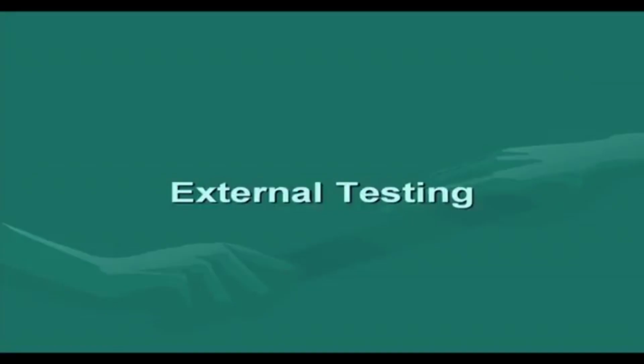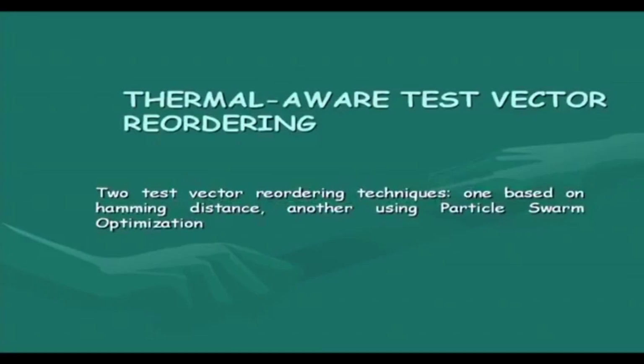We will classify this whole presentation again into the two parts that we were looking at previously. The first part is external testing, where the test patterns are stored in some automatic test equipment, and from the automatic test equipment the test patterns are transported to the circuit and applied there. A very basic strategy that can be followed is test vector reordering. We have seen that test vector reordering can reduce the test power, and similarly it can also reduce the temperature.